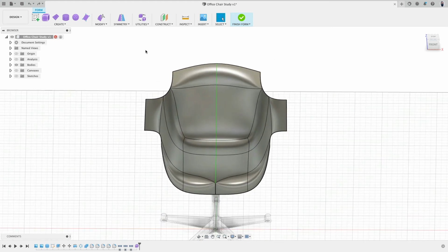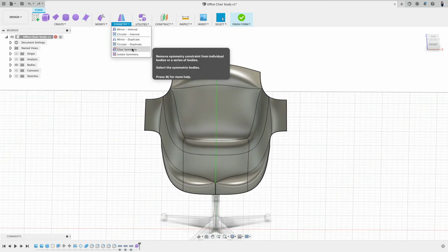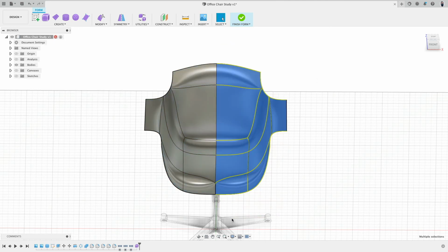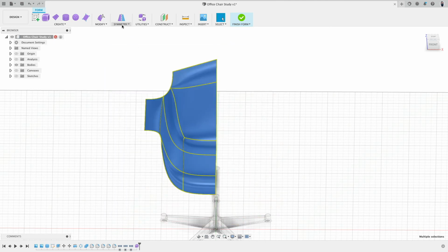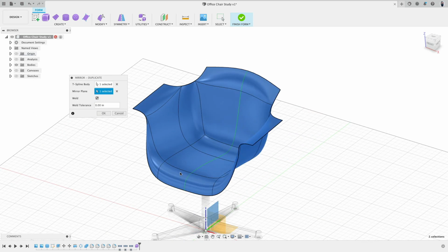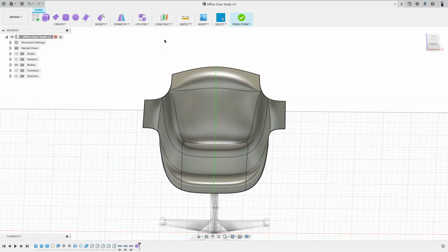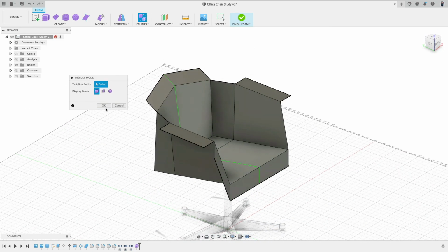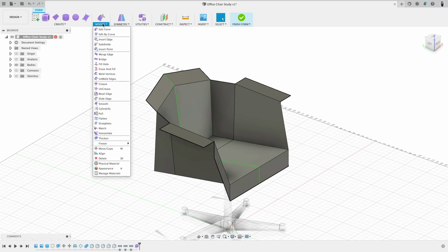That doesn't work, as you see. So we have to actually clear the symmetry. So we clear it and then we go back, select this, okay, silly symmetry, and then we just reapply the symmetry after. Now we did this extrude there. Easy peasy. If one way doesn't work, okay, we'll make it work a different way.